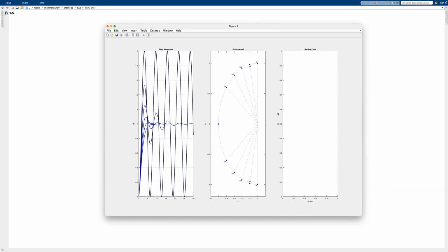Then there comes a certain zeta value that corresponds to the ideal path for the pendulum to stop at its first pass. What I mean by that is we release the pendulum and it goes down, and it exactly stops at that equilibrium point and doesn't pass through it a second time because it doesn't need to. So the amount of friction that is needed to basically run out of energy is called the critical damp solution, and that's zeta equals 1 in our system.